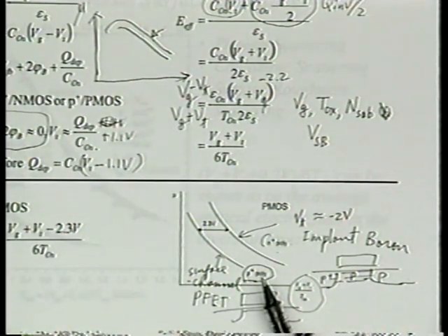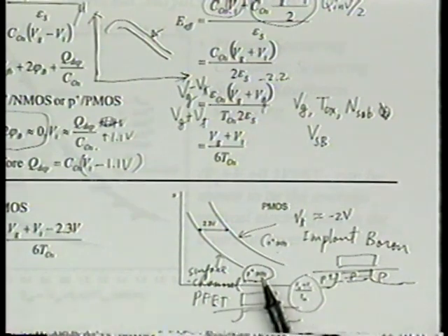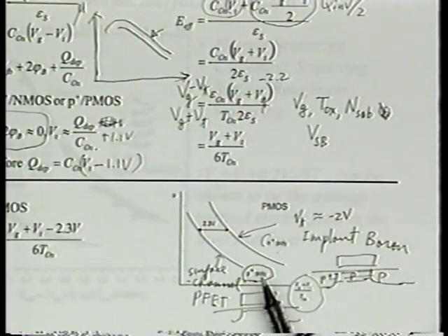All right, so what's the explanation therefore? In fact, that could help answer that question as well. Is it possible that both devices have carriers flowing at the surface and yet the mobilities are different? Is it possible? If you can answer that question, then you can say you've understood the topic that we covered today. That is why even for an N-channel transistor, the mobility is a function of vertical field.